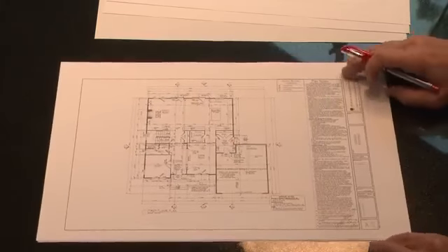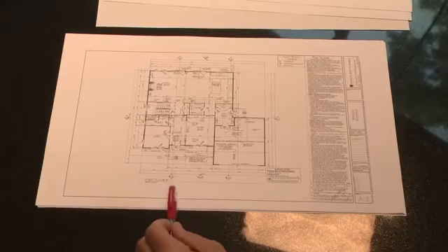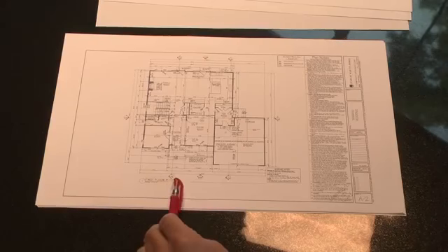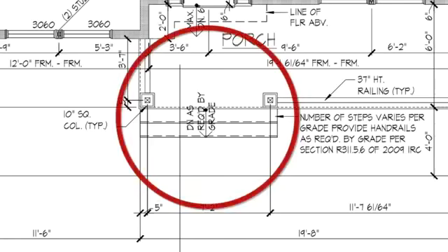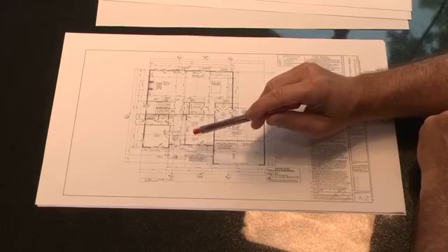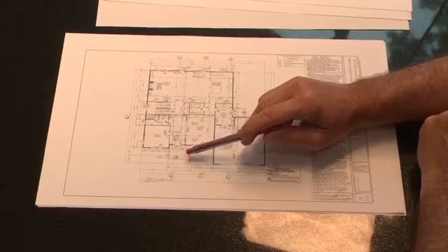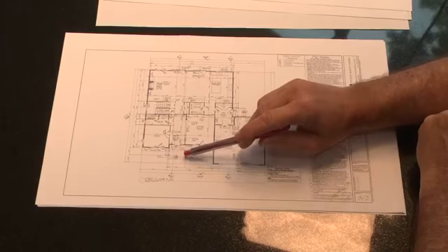So first floor, sheet A2. A couple things to think about. One is I like to start from reviewing the plans as if I were walking up to the house. So in this case, you can see there are two physical steps leading to the porch. When you get your design set, we're not sure if there's going to be 2 steps, 3 steps, 5 steps. So the architectural plan is not trued up to the site plan yet. So we show prototypically 2 steps.